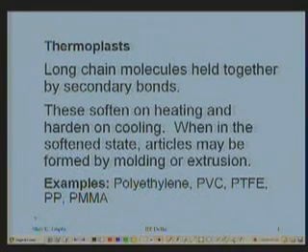Then we have PTFE, which also falls in this category. The market name is Teflon, polytetrafluoroethylene. This is one material which has a very high softening temperature, and it usually doesn't stick to anything. So your non-stick wares, cooking wares, you are having the coating of PTFE on them. And because of the non-stick quality, they are, to engineers, they also provide good lubrication as bearings.